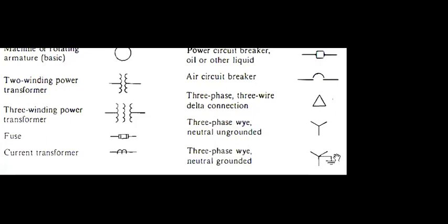That means in the neutral path, to limit the short circuit current or the unbalanced or fault current, you may sometimes have reactance in the neutral ground path. So regarding Y configuration, you have three different options.